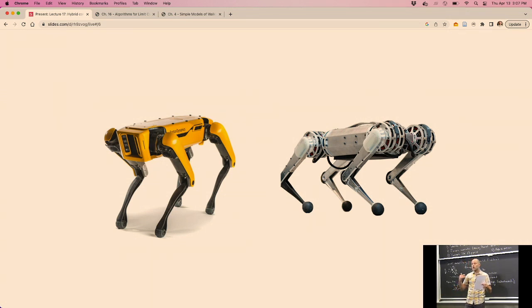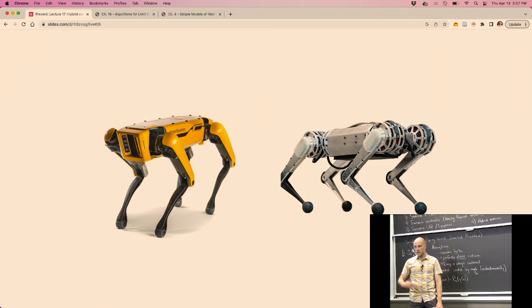It used to be some of our early stability metrics in legged locomotion were dominated by the most important time constant, which was the swing leg speed. How fast can you move your leg, right? Because that's what gives you the ability to do foot corrections. There's still things that are hard. If you ever want to test someone's humanoid controller, you see all these amazing videos of step recovery, and we've done it, but you rarely see videos of someone coming up and pushing the robot this way where it has to step across. That's a lot harder, right? There's tricks. There's things that are still hard. I think people can do that now, but for a long time it was like every robot video I ever watched, they were being pushed this way. It's not just chance.